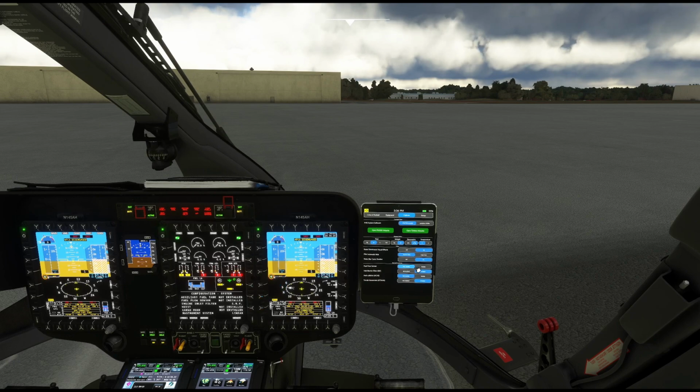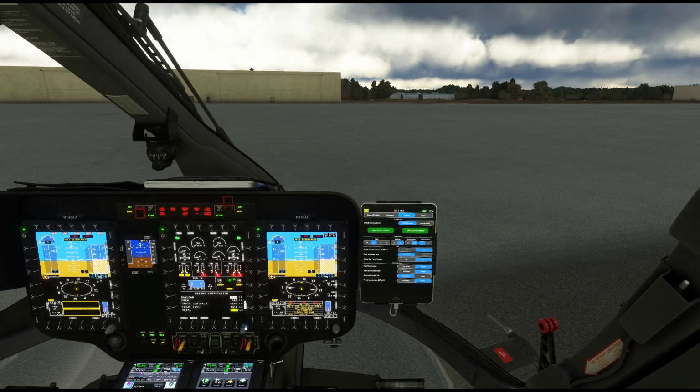All right. We do have flow sensors, so we'll go ahead and put those on. Boom. How about that? There they are. All right, and then the last thing on this is the weight. And so what we would do is I'm going to click here, and clicking that processes through. And I could say, let's say we got our 2 pilots, so 345 pounds sounds about right. Total fuel, let's go ahead and bring that up. And that is, yep, there's plenty of fuel right there. And then for our payload, let's go ahead and bring that up as well. I'm going to bring it up rather quickly, going right just below that total, and I'm going to validate it, and then I'll go previous, and you'll see right there, this is telling me that I'm legal to take off.